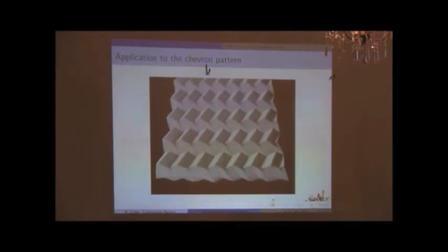Compared to honeycomb, where you have to glue alternating foils of aluminum to expand it and so on, this seems much simpler to produce. Actually, it's quite difficult to produce, because you must not stretch the foil, and it's not so obvious. All right. So I will use this pattern, this fold, as a core for my sandwich panel.